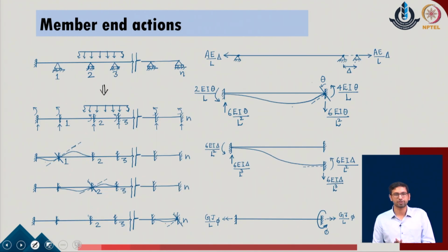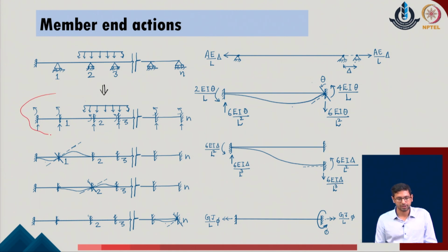As a further step, we now try to see the implementation of the given approach. We have considered a system which is subjected to some load. As a first step, we considered the system as restrained with all the degrees of freedom with respect to the external load, and we evaluated all the system reactions at the given supports. As a next part, we released the first degree of freedom in the given system.